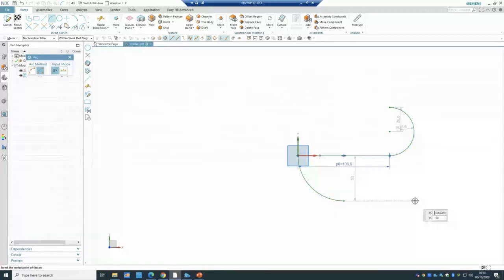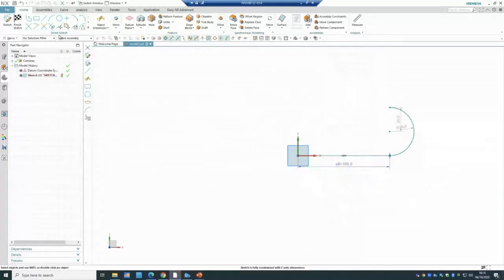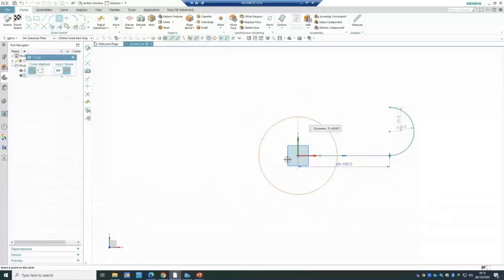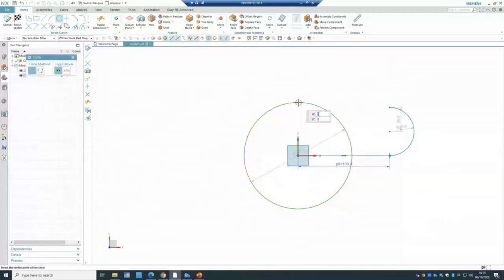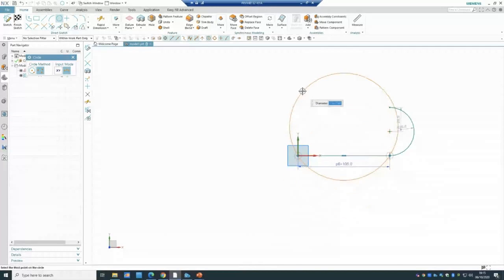So that's the arcs. The circles, the same things. I was saying that you can either have them, let me delete this one, by the 2 points, a center, and the point that you're going to finish, which technically drives the radius or diameter of the circle, or you would be able to just do it with 3 points that you want to make that circle.